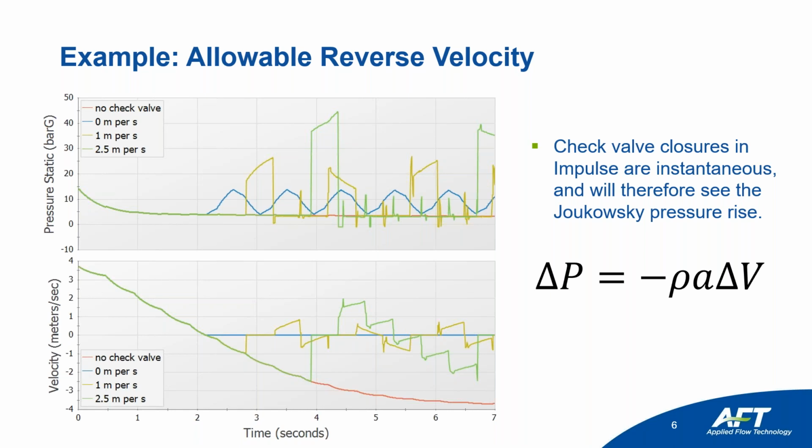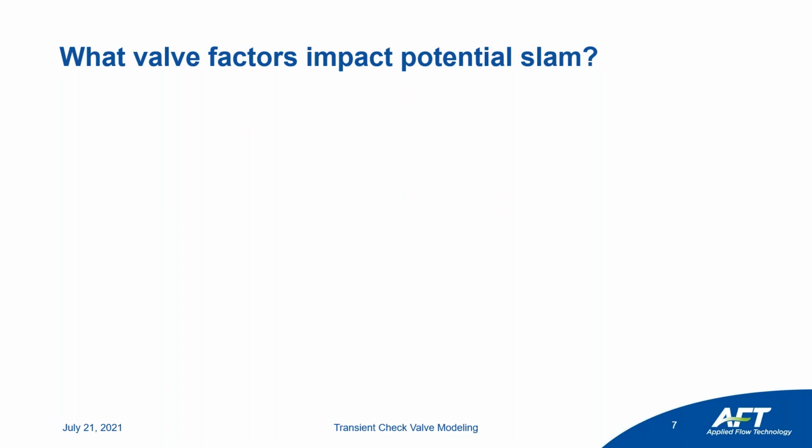And that we have to get back into the concepts and think more about how these check valves are operating, and some other thought process that has gone into check valves as a science, right? So we've looked at the system components. If there's a higher elevation gain, if there's more driving force for reverse flow, the harder it's going to be for your check valve, as well as the faster you decelerate. So the faster that you go from 100 meters per second of flow, I hope you're not flowing that fast in your pipes, but the faster you go from that high velocity to 0, the harder it is for that check valve to react. And that's going to largely depend on the valve itself as well.